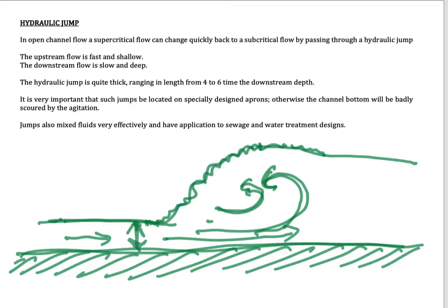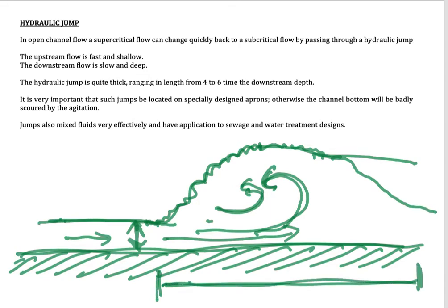After the hydraulic jump occurs, the energy is released in this situation, so the depth will go back to normal. It takes a certain distance from the hydraulic jump to return to the normal flow. Okay, so this is what we need to take care of if we have an open channel, because sometimes the damage is very severe, and it could break the sewage drainage.